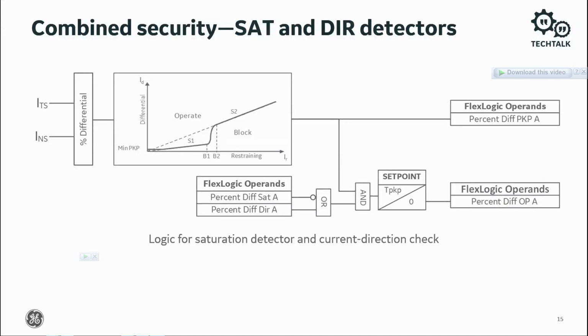Typically, external faults near rotating machines result in very large time constants in the fault currents. Similarly, upon energizing a step-up transformer, the inrush current is limited only by the machine impedance. In addition, sympathetic inrush can provide very significant and long-lasting currents. The relay uses saturation detection to provide additional security against improper operation during these events.